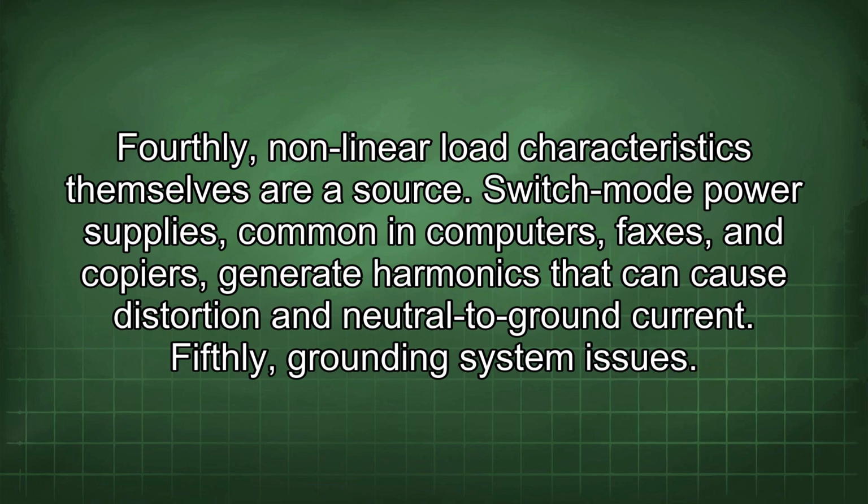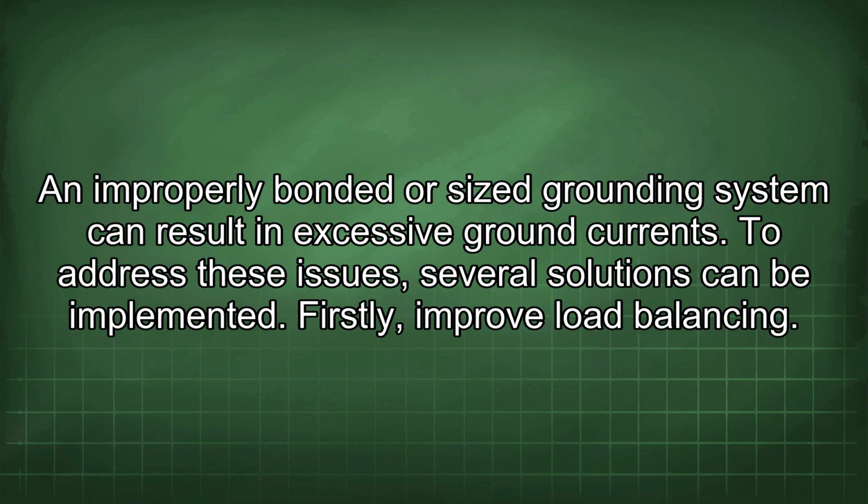Fourthly, nonlinear load characteristics themselves are a source. Switch mode power supplies, common in computers, faxes, and copiers, generate harmonics that can cause distortion and neutral to ground current. Fifthly, grounding system issues. An improperly bonded or sized grounding system can result in excessive ground currents.